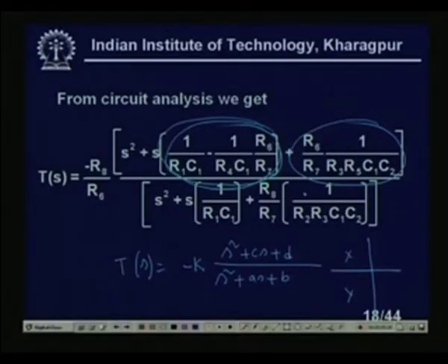So, this is the only difficulty in this type of state variable structure, otherwise it is a tremendous advantage. Its sensitivity is also quite low, and its tuning is a great advantage. In the next slide I can show you what are the different elements we can choose to tune omega p, Qp, omega z, Qz independently, right. Because as you know, in the filter parameters we have to tune omega p. You can take another pen.